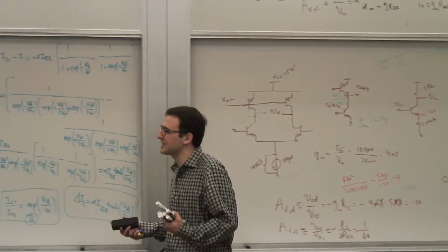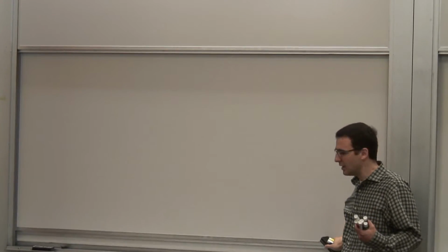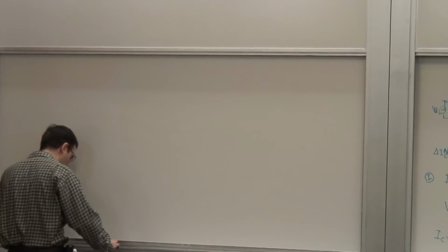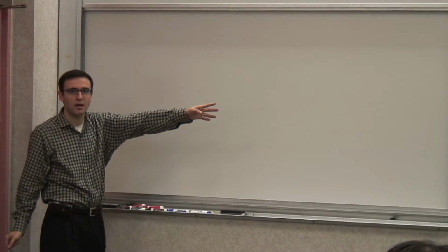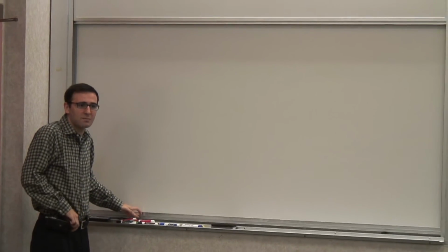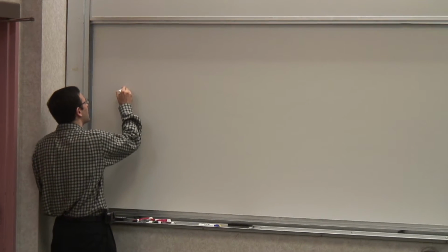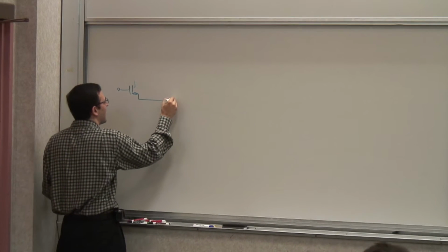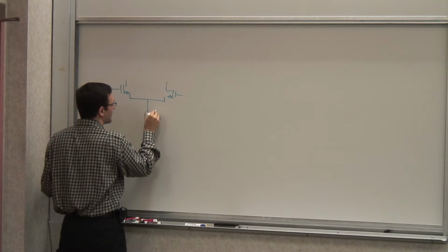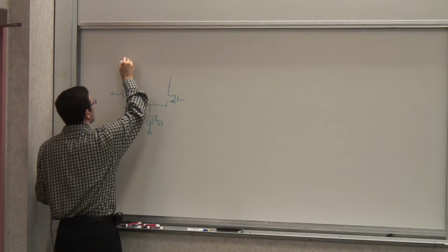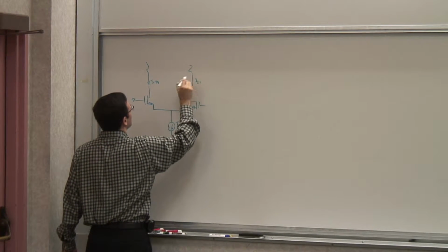Now you can see everything we said pretty much is applicable in terms of principle to the MOSFET version. Now the difference is that MOSFETs follow a different set of equations. So if I try to calculate the large signal transfer function like we did for the calculation that led to the hyperbolic tangent, it's normal to expect something different, right? Some kind of different behavior. So let's look at an equivalent pair of NMOS transistors placed in this arrangement. This is ISS, and we're connected to some sort of load, and this is ID1, this is ID2.